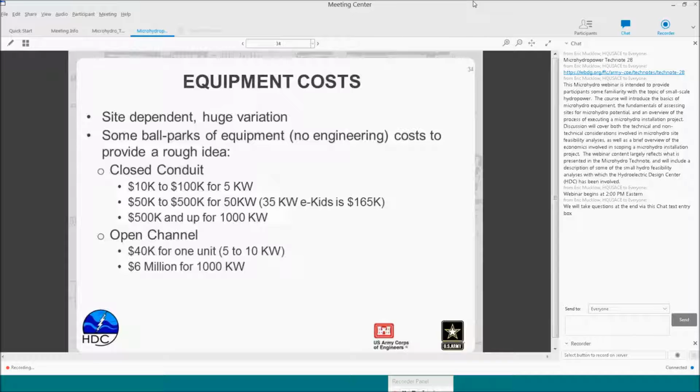With large powerhouses, you can find cost projection curves that relate the size of the facility in terms of megawatt output to the expected cost of constructing that new facility, but this predictability does not really extend to the microhydro scale, as unique situations may drive construction costs by full orders of magnitude. These costs I have listed here are for rough estimates of equipment only. Those variable civil construction costs are not included. Also not included are engineering costs.